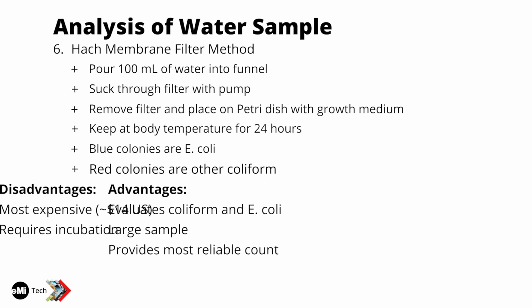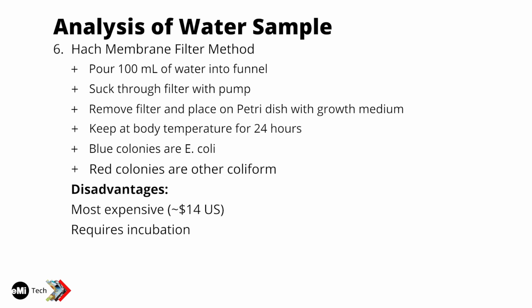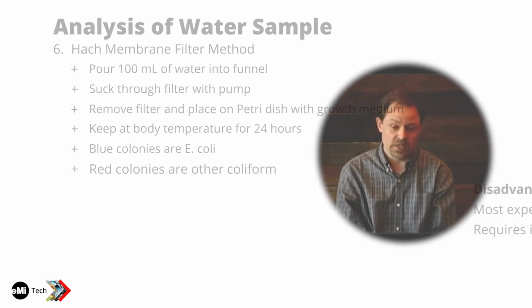Disadvantages. It is the most expensive among the tests that I've talked about. It's about $14 per test. It's got bulky equipment. You have to have the hand pump and these large filter units. Those are disposable. So for every sample, you have to have the whole filter unit. And it does require incubation.